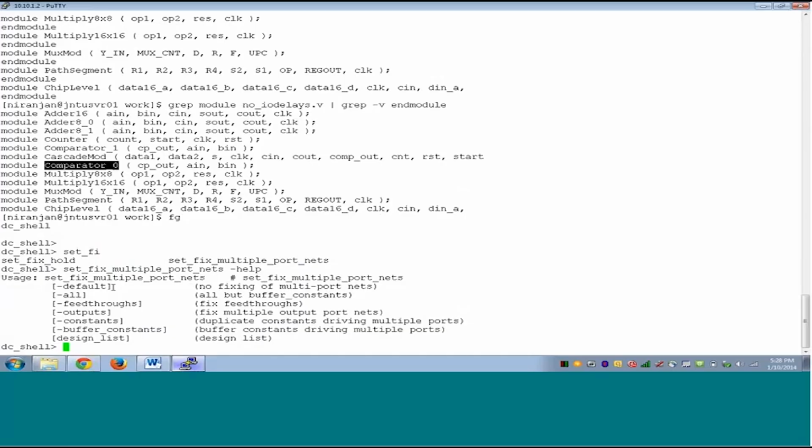But when it goes to physical design, many times these kind of assign statements will create issues. So always you want that there should be a buffer separating output and input, at least a buffer, and then according to design rules there will be more buffers or the buffer will be upsized. Also you might have a case of one register driving multiple outputs.